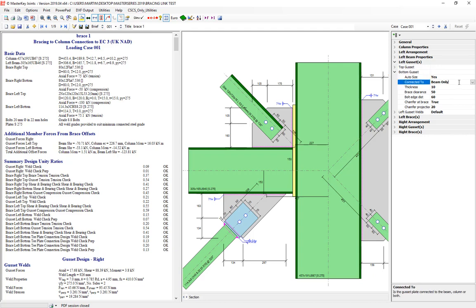But just to say that in this instance we're more like a knuckle brace, as we call it. Again, the brace is auto sized. We've said that it's connected to the beam only. If I want to configure that a little bit more, I can of course turn the auto sizing off and then begin to experiment with the chamfering. So I could have this, for instance, coming down here and up and out by modifying the chamfers on each of the 4 corners. Let's just set that back to auto size.